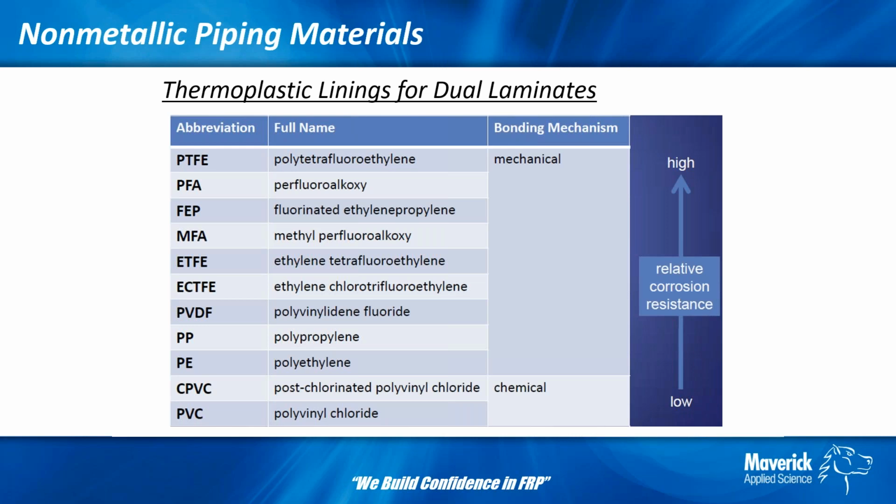It should be a controlled process where it's regulated and measured, and it's definitely not something that you would be doing by hand. In the field, say you're joining pipe and you require a post cure on the pipe and the joints. We might apply, not a heat gun, but a heating blanket around the joint and require the joints to be post cured with a heating blanket for so many minutes or hours, to make sure that the joints are equally as cured as the pipe itself, as a field operation.